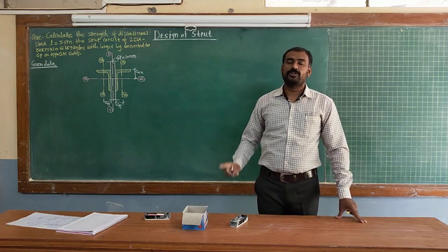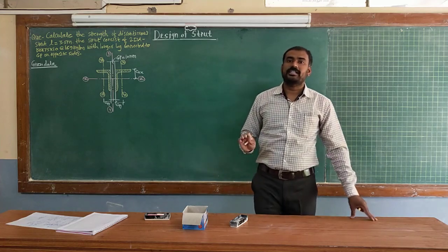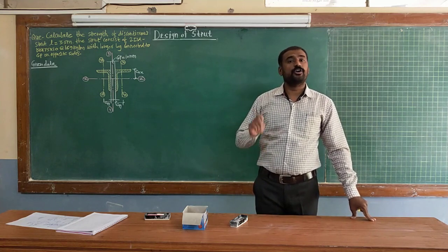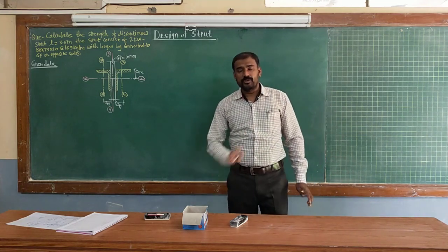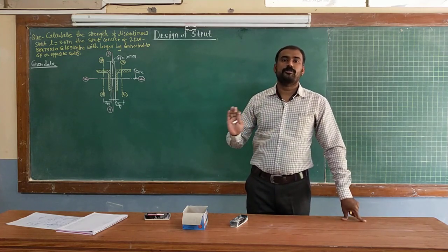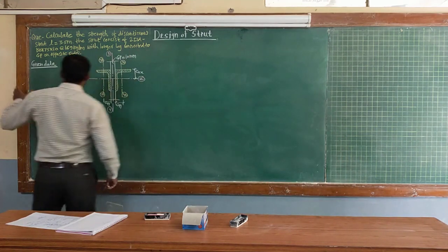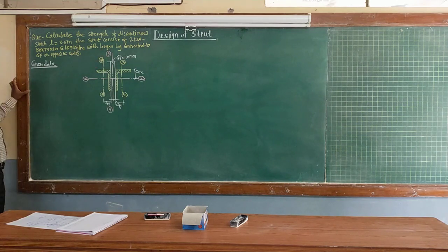Correct? Here you need to assume constants k1, k2, k3 depending upon the type of connection given, whether it is a single bolted or double bolted kind of connection. In case of a double angle section, the regular procedure is to be adopted, that procedure which you adopt for design of a regular compression member. Correct? So initially starting with the first step of given data. So for the given data, calculate the compressive strength of a discontinuous strut of length 3.5 meter.